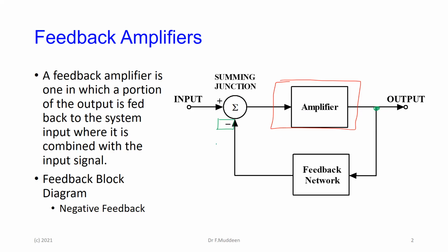We also saw, as a revision, that there's a version of this circuit where we take the feedback and supply it in a positive form. And when we do that, we create these devices called oscillators, because oscillators are unstable. Remember what an oscillator essentially is: with no input, you get a signal coming on the output. That is something we do deliberately. It is a deliberately unstable amplifier, where we want the output to be going up and down, but in a predictable way.